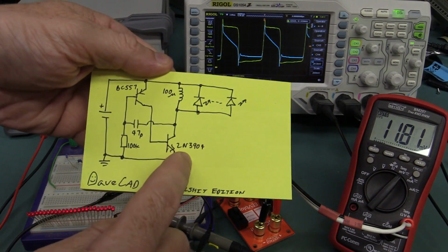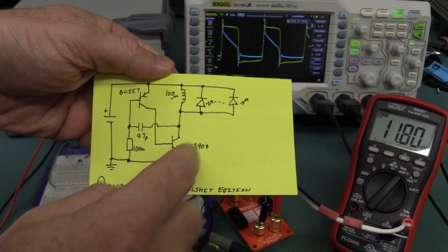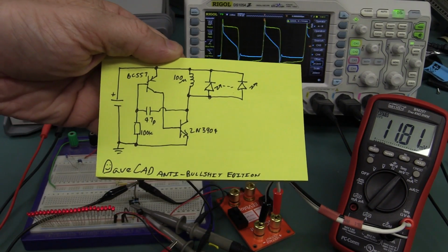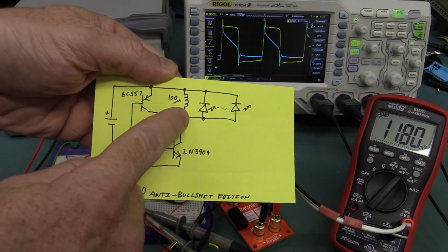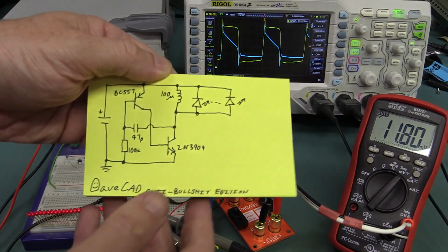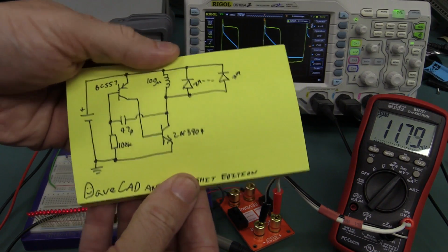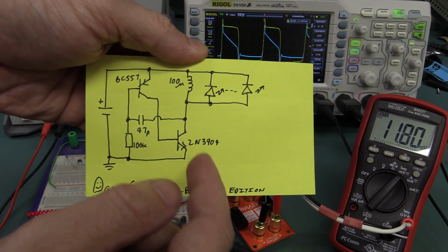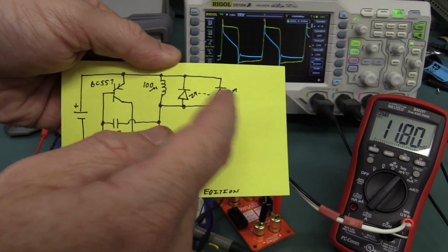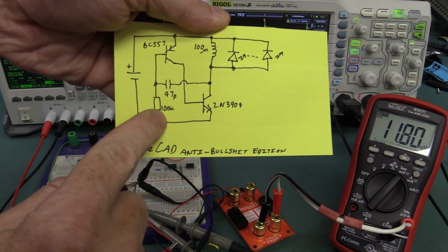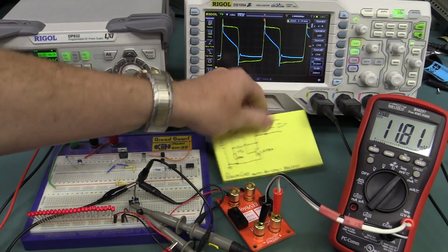I've got a 2N3904 in there. That's a reasonable general purpose amplifier. We've got a BC557 up there. I whacked in a 100 microhenry inductor. That's a little surface mount job down there. It's a bit higher than the 88 or so we calculated from the five cores, but yeah, near enough. And exactly the same values, 47 picofarad feedback cap and 100k down to ground.